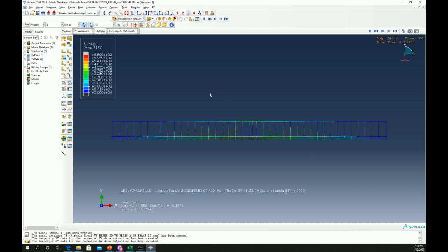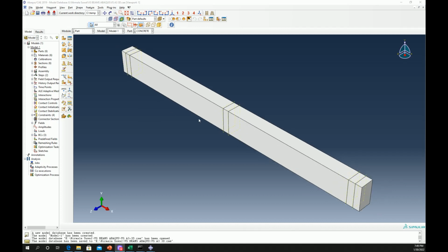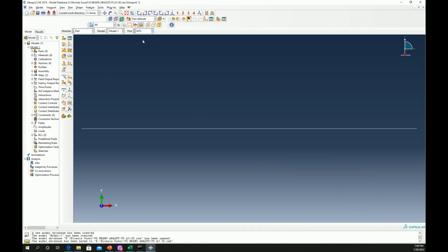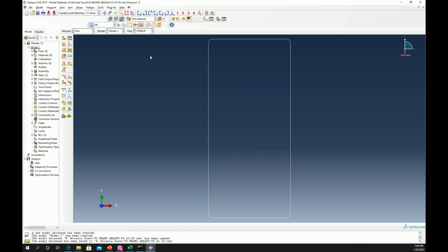So we will open our another Abaqus interface. This is 3D modeling in Abaqus, where we define our concrete model as a 3D. And similarly also the rebars, they are defined as wire element truss type M25, M30, and the steel plate, it is in 3D. We have defined its length, width, and the depth. Also the stirrup, now we have vertical legs as well as horizontal legs.